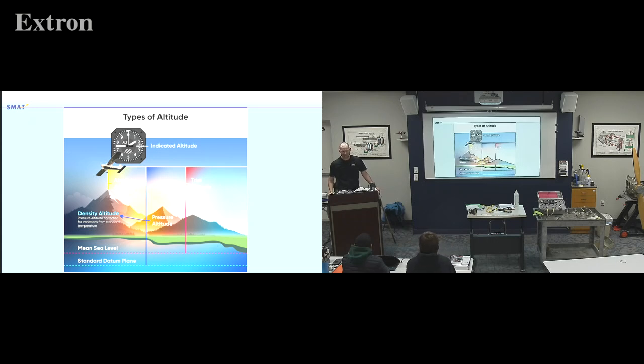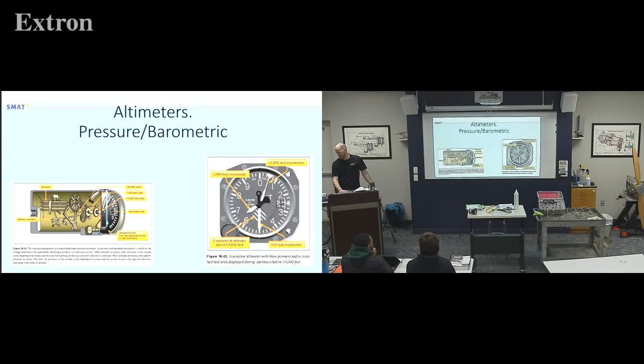Is my altimeter going to say you just got higher, or you just got lower? Lower. Colder air is more dense, so it's going to say you just got lower. I believe that's right. That's more of a pilot question, but it affects things a little bit, but we're not going to go into that detail.